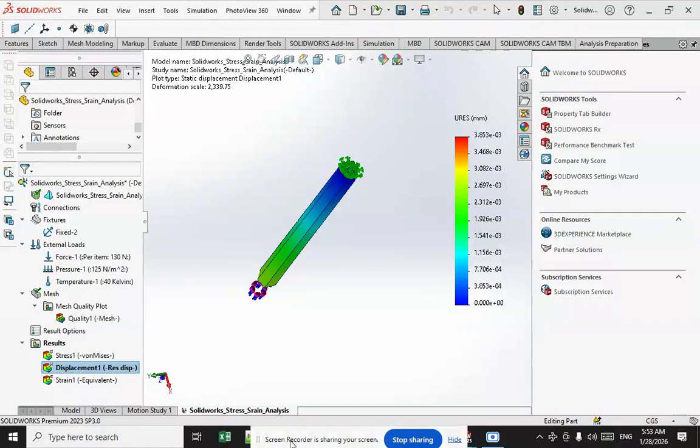The external body forces will appear as the independent right-hand side term in the differential equations, while the concentrated forces appear as boundary conditions. An external applied surface force, such as ambient pressure or friction, can be incorporated as an imposed value of the stress tensor across that surface.